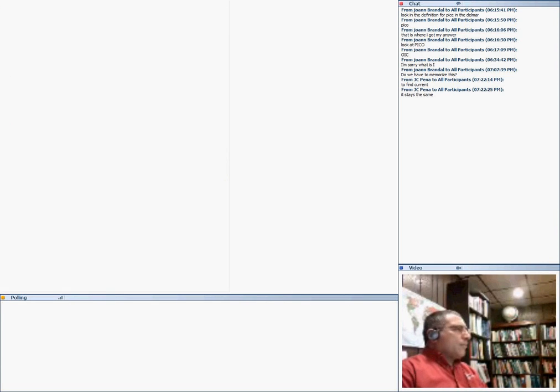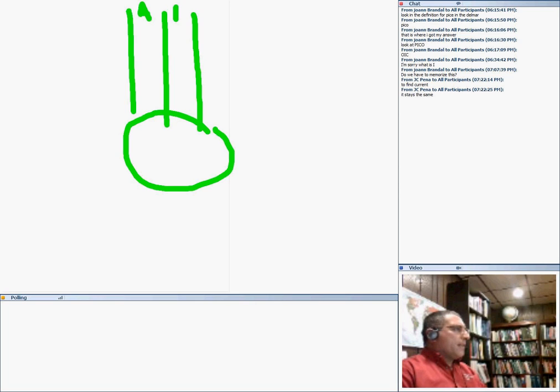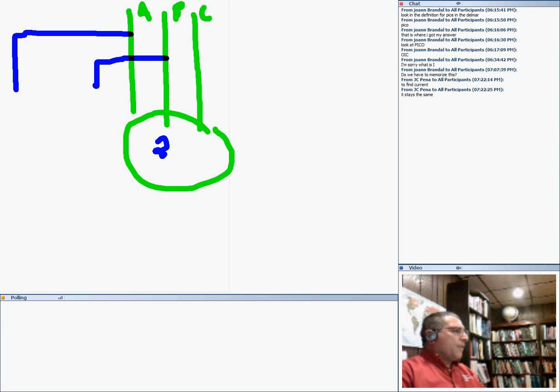The one I want to show in the series circuit is the control circuit, the magnetic starter control circuit. I know you haven't done that before, but I'm going to quickly show a three-phase system going to a motor, and I have phase A, phase B, and phase C, and I want to take some of the phases to drive a control circuit. I'm stealing from phase A and phase B to show a control circuit. This is a 240 three-phase motor.